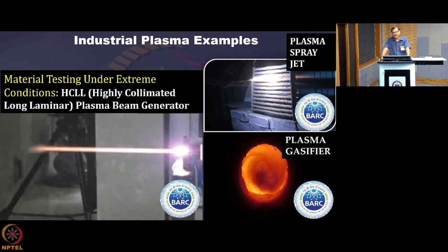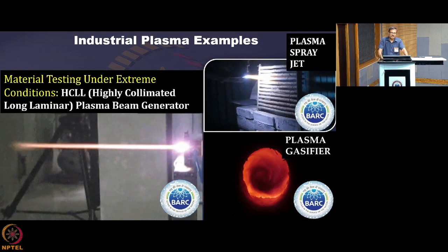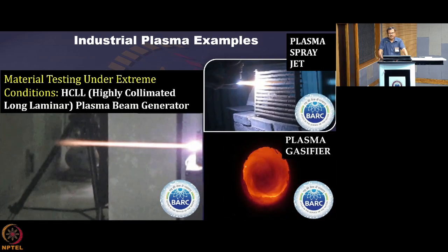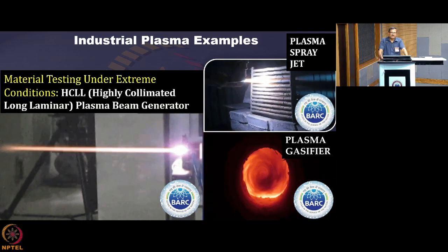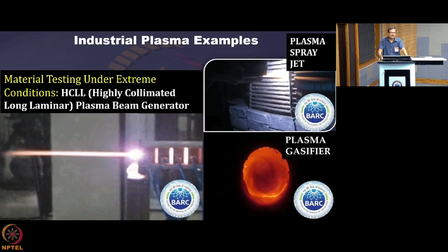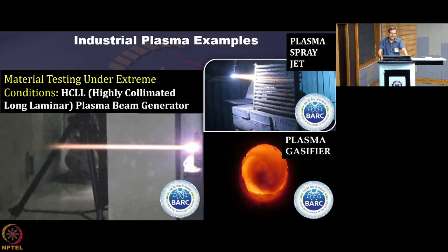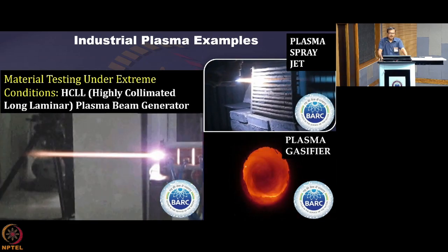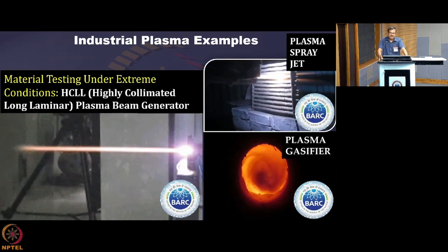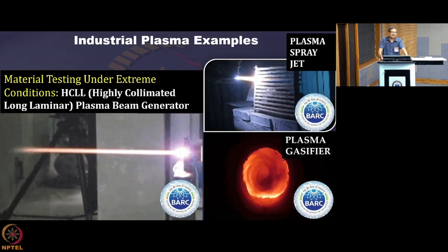That will be a thermal barrier coating, and it will be an environmental barrier also, protecting the surface from environmental deterioration. Very high temperature materials are usually oxides, and their melting point easily goes more than say 1500 degrees centigrade. Some of the materials commonly in use are alumina and yttria. Alumina means aluminum oxide, yttria means yttrium oxide. Their melting points are extremely high.